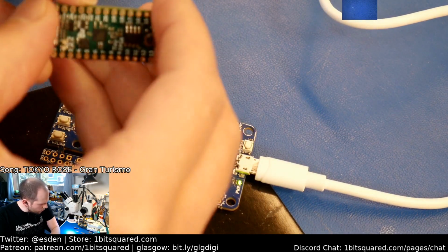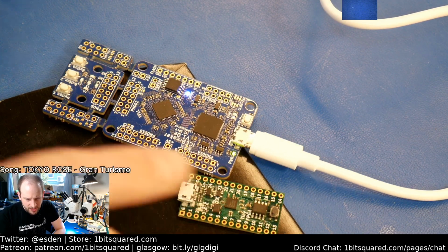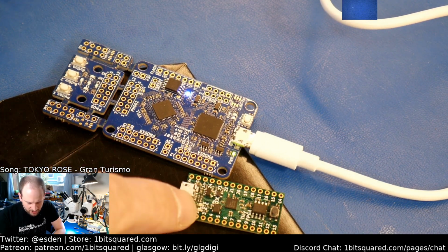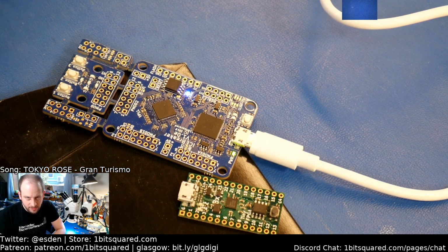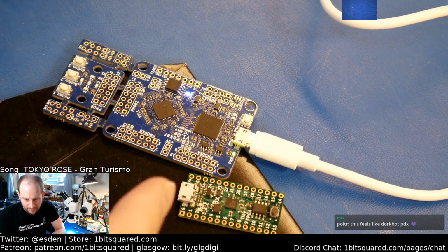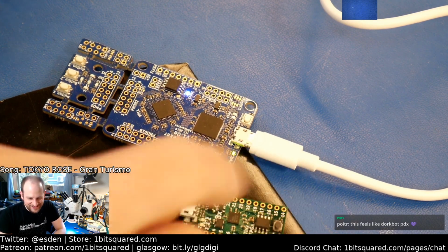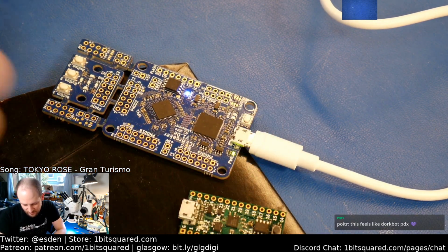So what he did is use a functionality of the FPGA that has a special warm boot functionality. So essentially, you load a bit stream into the FPGA that implements, basically it talks over USB.